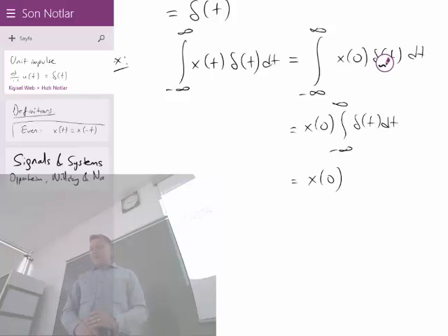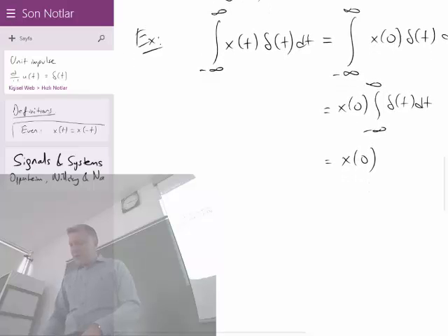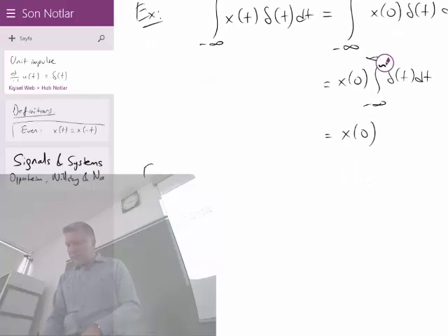Now, we are going to use this impulse for picking a sample from a continuous time signal. The methodology to extract x0 will be multiplication by an impulse and then integration. That's how we will sample the signal at t is equal to 0. Clearly, you can also sample the same signal at other points as well, right?